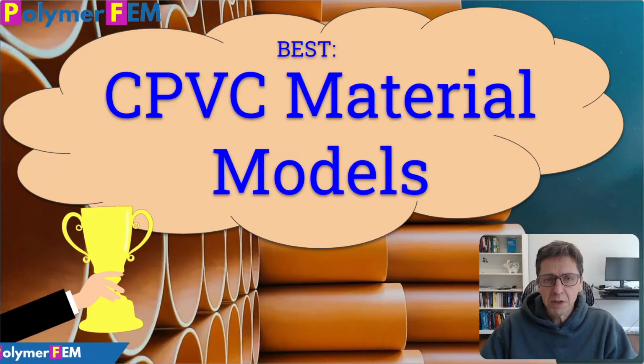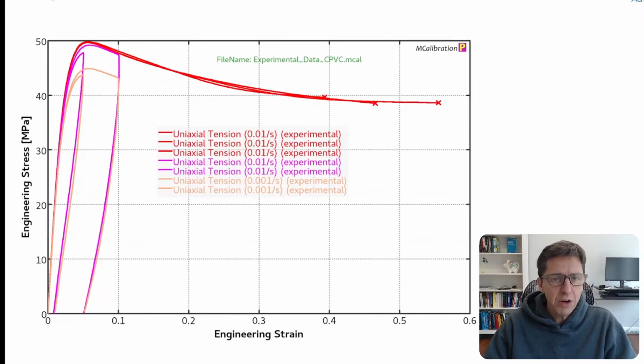So today I will talk about what material models work for this type of materials and what we can learn from this. So here's the experimental data that I have. It's uniaxial tension and two different strain rates, both loading and unloading, and there are multiple repeats of that. It goes up to large strains, and it contains some interesting information about this material. If I wanted to calibrate a compressive response, I probably would do some uniaxial compression testing as well. With this data alone, I can't distinguish the yield stress in tension and compression, but it's still a good data set.